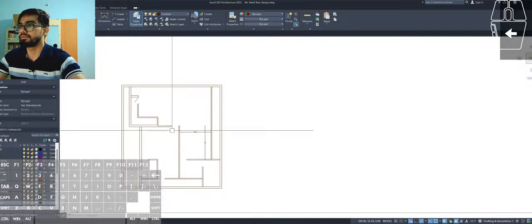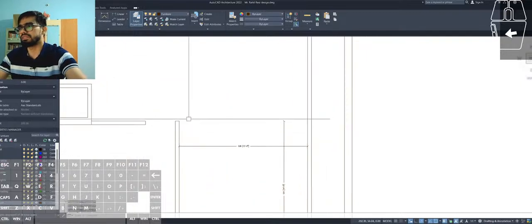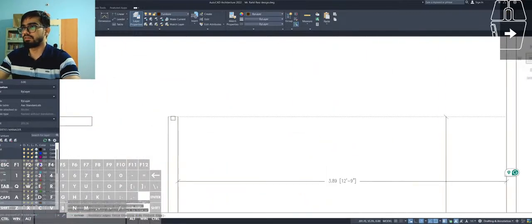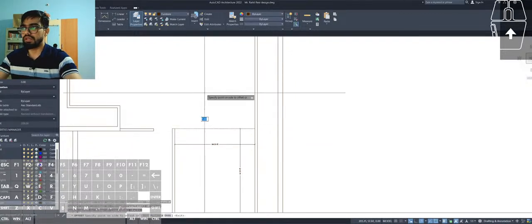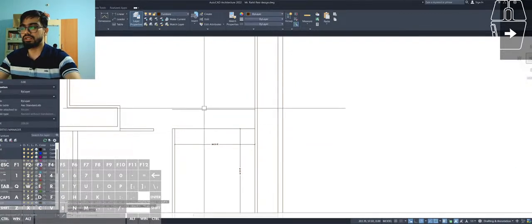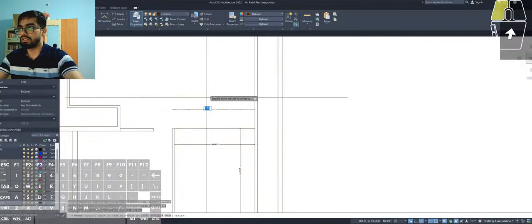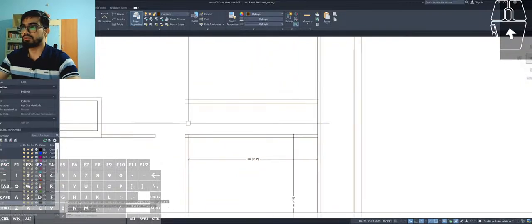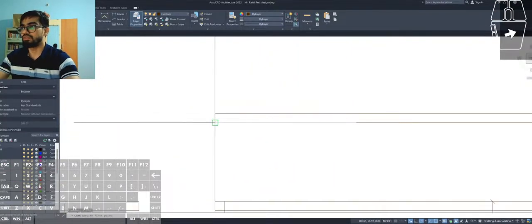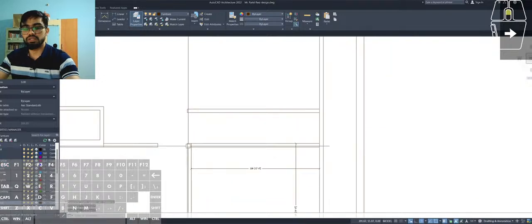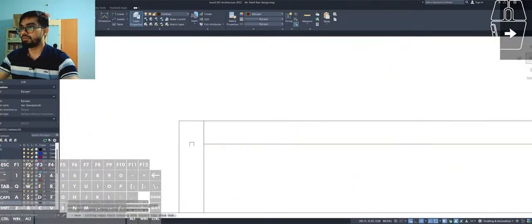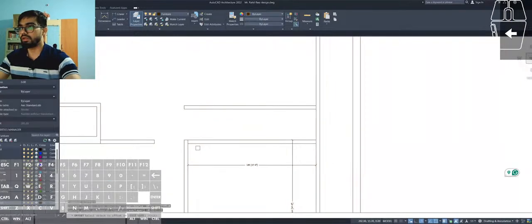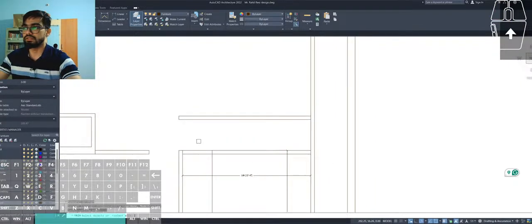Yeah, we'll do that because that maintains privacy, and we need privacy, even if it means slightly more complicated drawing. We'll have an offset of 1 meter, and then the wall thickness is 0.115. We join this, and then we remove this part, offset 0.9 for the door. 0.9 is 3 feet approximately.